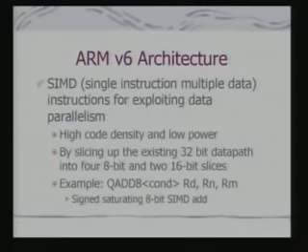and that is put in the architecture in the J mode. The other enhancement which has come in with ARM version 6, which is again an enhancement to target DSP applications, because if it is going for mobile and other applications, you will find that your speech, your camera, your video, these are all signals which are to be processed. So one of the interesting features in ARM6 is SIMD instruction set. This provides high code density and low power. What is SIMD instruction set?